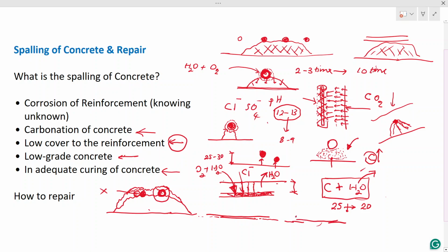Usually we do the welding here to make sure of proper bonding. Generally we keep 10 times D for the welding. This is a general norm, but you have to make sure adequate welding length is there. This will vary, maybe 10, maybe 20 times, depending on the condition of the concrete and the requirement. So this is the general value, and we lap the reinforcement like this. During the welding, you have to make sure the reinforcement is not damaged. A qualified welder shall be used for this kind of purpose.